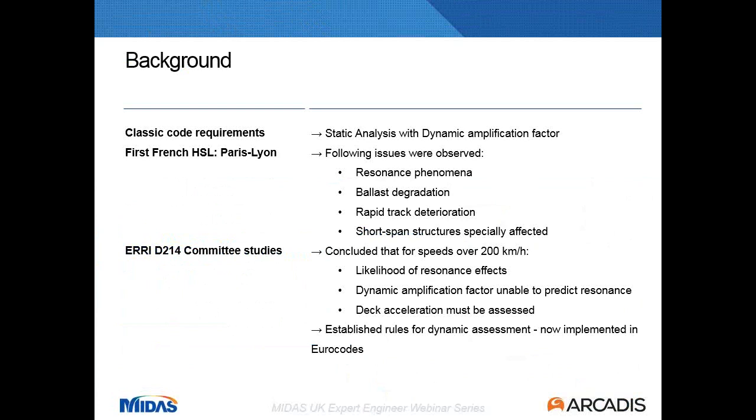But it's just a series of static analyses that you are checking. You extract an envelope and then you multiply by a factor, a dynamic amplification factor, to take into consideration the dynamic effects. And this classic approach was the one that was used on the first French high-speed line between Paris and Lyon.